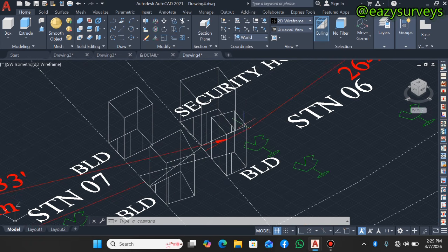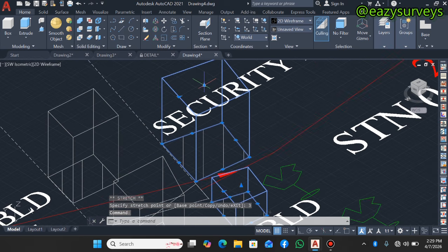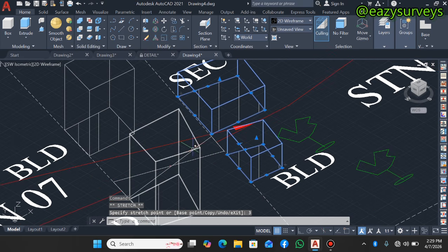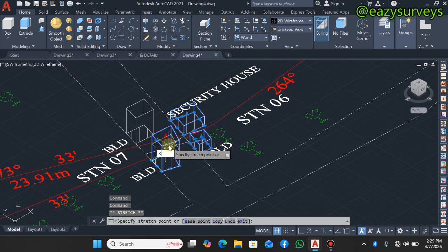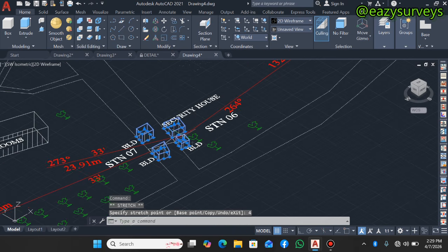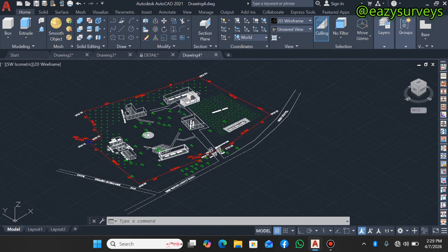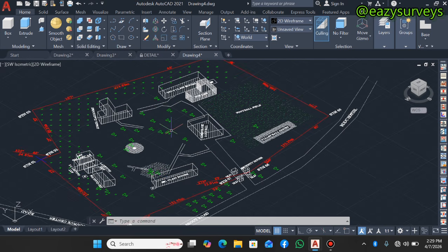However, the security post here, the security houses, is about just a little bit, about 3 meters height. So I'm just going to select, click on the above rectangle icon, then type 3 just to reduce the height of the security houses, not to be taller than the actual building height. Okay, this one is about 4. Okay, so I'm done changing that. Also, there are some buildings that are less than 8 meters. I'm just going to edit that as we forge ahead.